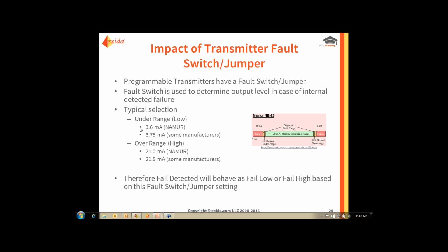If my standard signal is 10 milliamps, and for whatever reason I go to 8 milliamps, we would probably classify that as a dangerous failure, because it could also have been that it went from 12 to 10. You remain in the healthy operating range. You're at a stuck output. You can no longer follow the process value. So at that point, the conservative approach is to call it a dangerous failure.